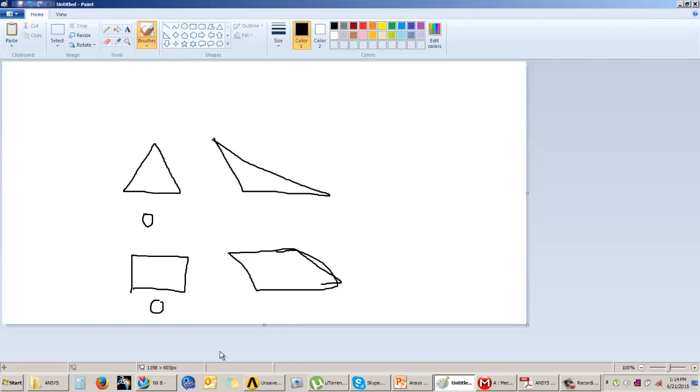Now in skewness, if the skew value is 1, that means it has completely distorted and the element is degenerated, meaning it has not created that element. If the value of skew is from 0.9 to somewhere below 1, then you can say that they are bad elements. The elements have distorted and they have become bad.